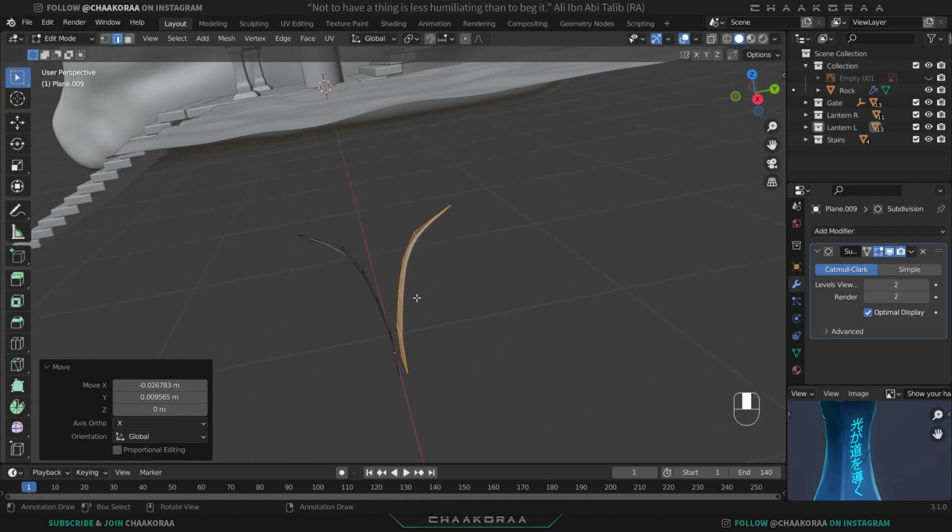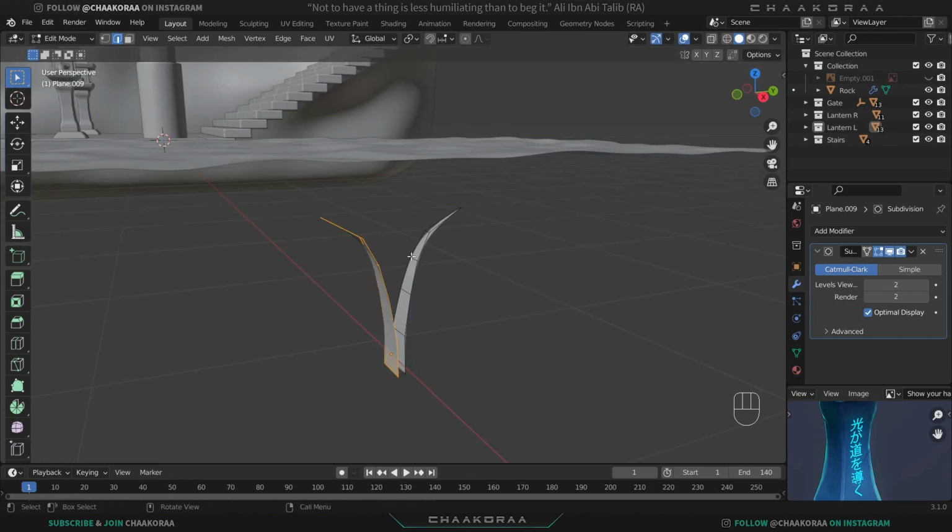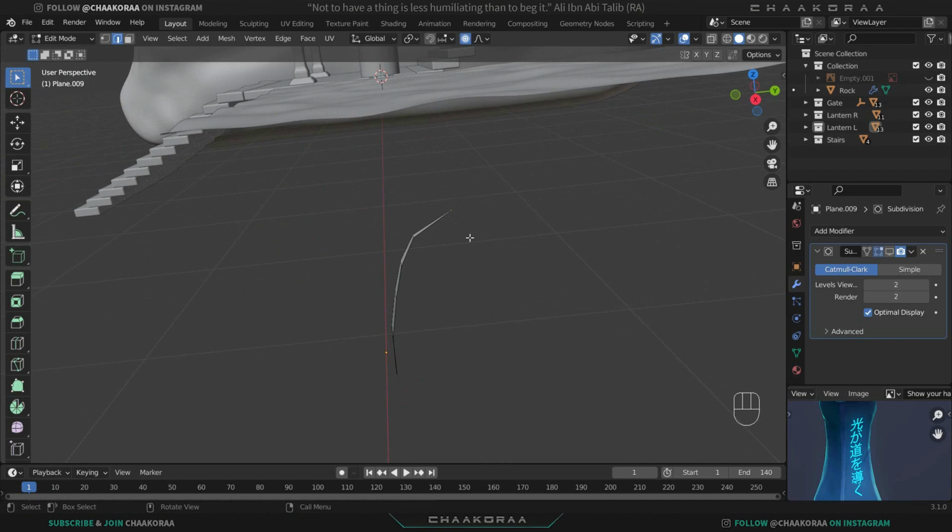We don't want this. With this shape selected, press Ctrl I to invert the selection and press H to hide it. But you see that it doesn't work. It's because this subdivision modifier is on. Let's disable it for now and press H to hide it. Because we're going to change this shape, I don't want changing this shape to affect the other one. Press O or select proportional editing, turn it on, and let's change this shape.